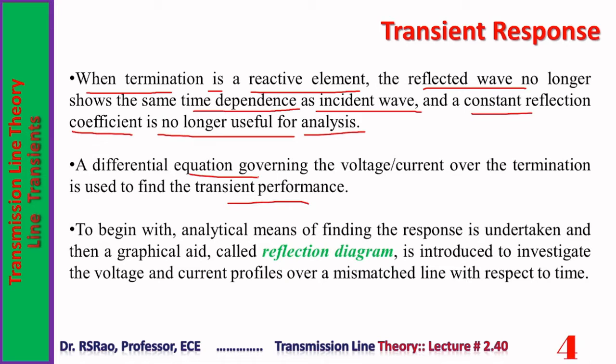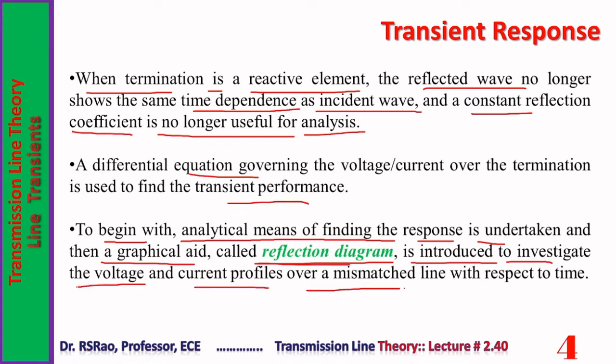You have to go for a differential equation which governs voltage and current over the termination for finding the performance of the line. To begin with, analytical means of finding the response is undertaken, and then a graphical aid called reflection diagram is introduced to investigate the voltage and current profiles over a mismatched line with respect to time.